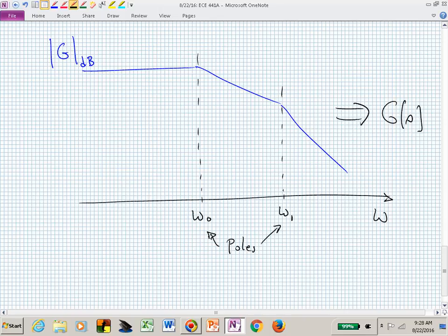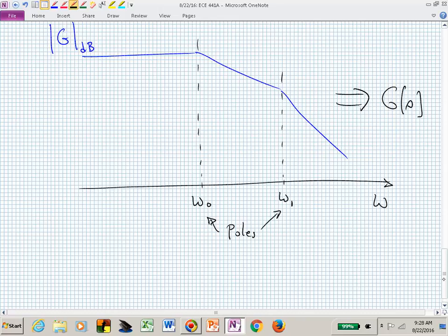experimentally. And you could go into the lab and excite your system with a given frequency, and it will reach a steady state, and that steady state now tells you what the magnitude and phase is at that frequency. And if you did that for an infinite amount of frequencies, you could reconstruct this magnitude plot. And that's what your machines do when you push a button and say, give me the frequency response of this system. It effectively does that. It excites the system and looks at it, and then it gives you that magnitude and phase information.